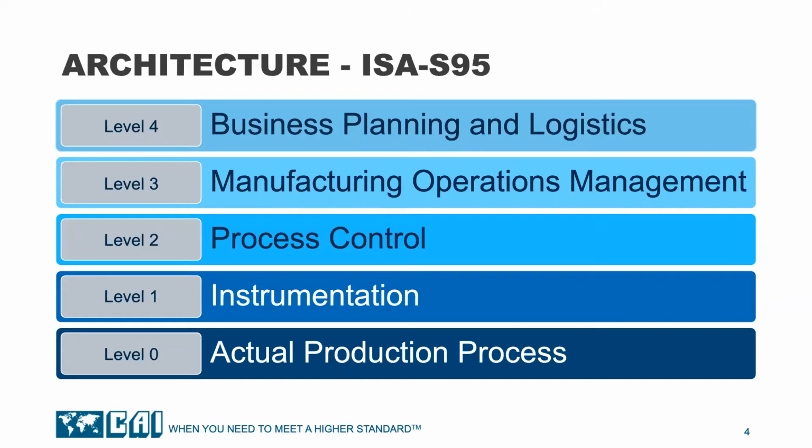And like ISA S88, the batch process control standard, many suppliers and several large pharmaceutical companies have adopted ISA S95 as a platform. The hope is that with greater adoption, integration between systems will become increasingly easier. Instead of implementing an interface between SAP and Syncade, Emerson's MES product, we might be implementing a standard ERP interface.